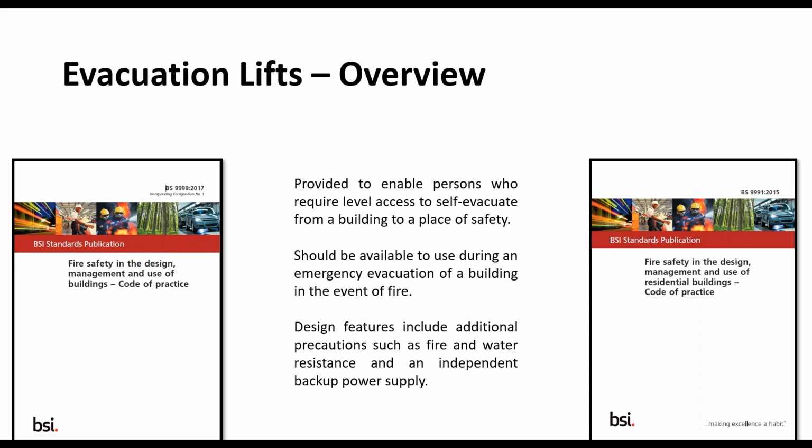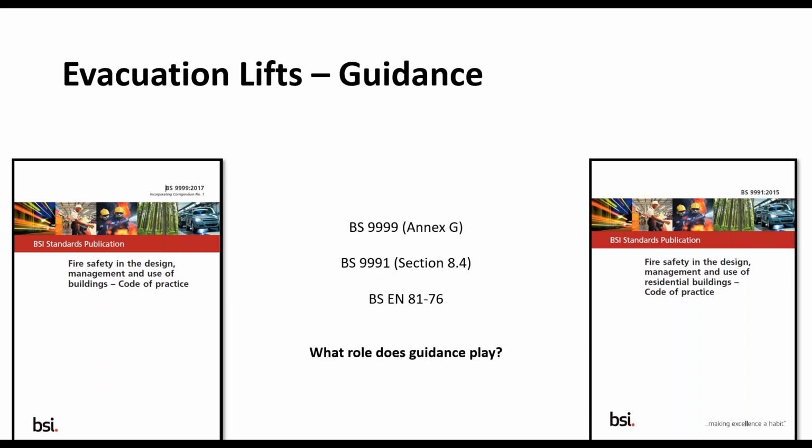Where do we turn to for this guidance? Well, as we move on to the next slide, typically we move to access BS 9999 and specifically Annex G, and BS 9991, and amongst other sections and annexes, 8.4 of 9991 begins to discuss those requirements in the unmanaged residential scenario in particular. The BS EN 81-76 is a very interesting discussion in its own right. I suspect there's probably a broader conversation to have around that, which we might expand upon in the Q&A section, so I won't labour that point here,